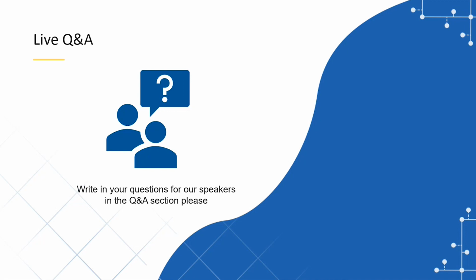Okay. There's another one here about live data. Is the utility network editor able to take live data from other systems and play this back so that the live status of the assets is also indicated? Maybe one for Ben. I think the answer to that would be yes, but it's not necessarily UNE itself. If someone's talking about reading information from, say, a sensor, you could use something like ArcGIS Velocity to read that data and then bring it into the system. And as long as it makes its way to a feature service, then the utility network editor can show it.